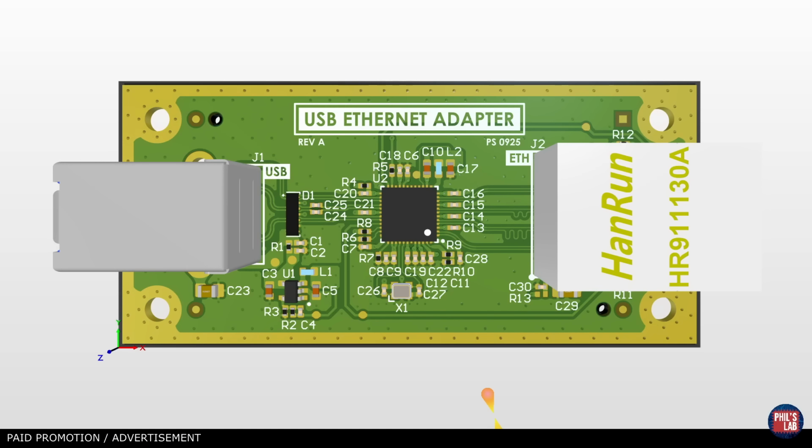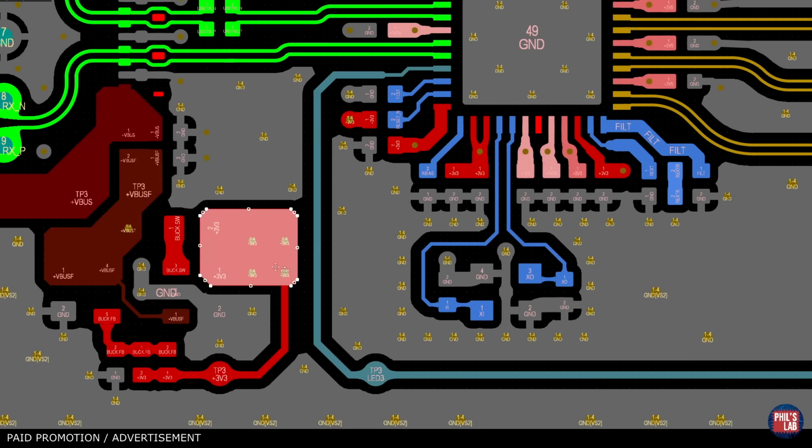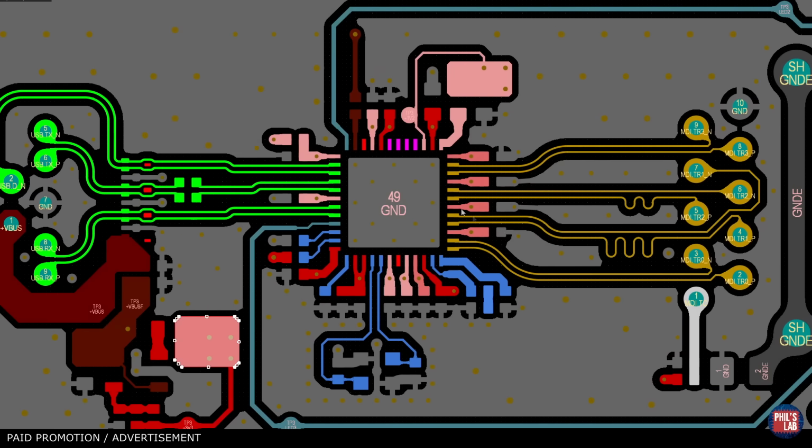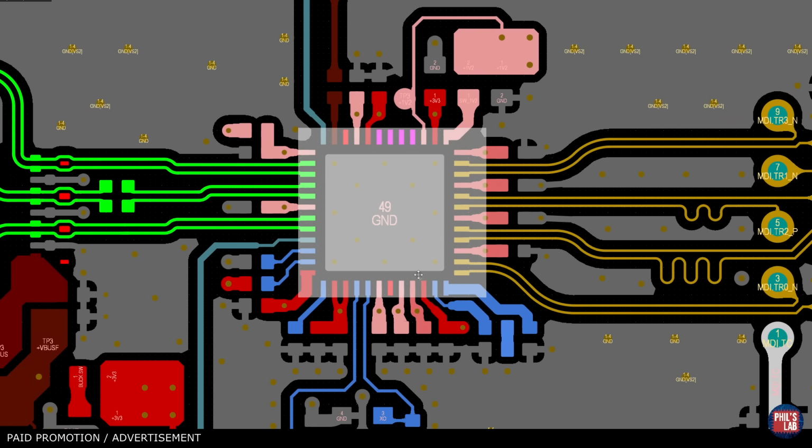In this video, I'd like to show you how you can perform a DC drop analysis and simulation using Siemens EDA HyperLynx. For this, we will use this USB Ethernet adapter demo board. I'll show you the process of exporting ODB++ data and what you need to pay attention to in Altium Designer and importing that into HyperLynx, and then performing DC drop analysis on a 3.3 volt net that feeds various polygon pours through vias, through decoupling and bypass capacitors into the USB Ethernet physical layer.